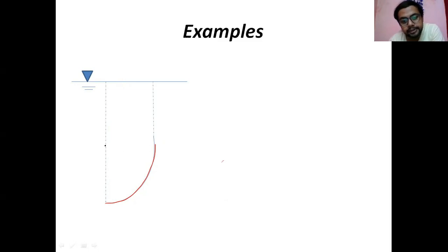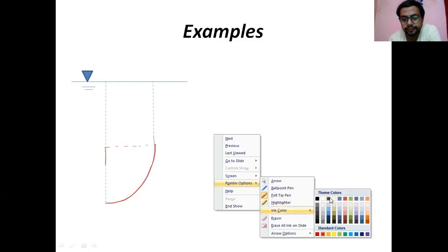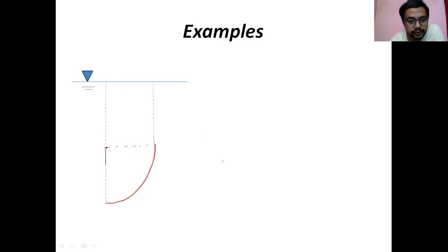If you project this curved surface onto this plane, it will look like this. I should use a different color so it is better understood. So here, if you project this curved surface, it looks like this. The other side is the unitary side. This is the projected surface. It is a plain vertical surface, there is no doubt about it. So over this surface, what force is acting? That is the horizontal force.